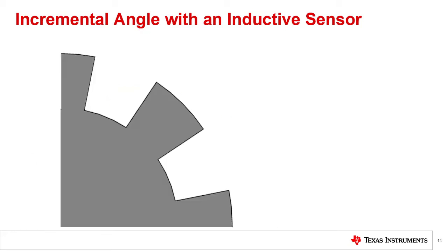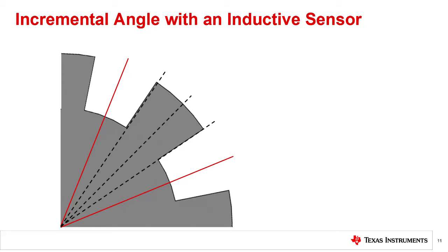To begin, let's first consider just one sensor pair. We continue to need each coil 180 degrees out of phase with its mate. If we let each tooth and half of each of the adjacent notches represent one full output cycle, then we might subdivide this region into 4 positions that each represent 90 degrees electrically. With this format, the coils require a separation of 2 spaces to achieve our desired 180 degree offset.